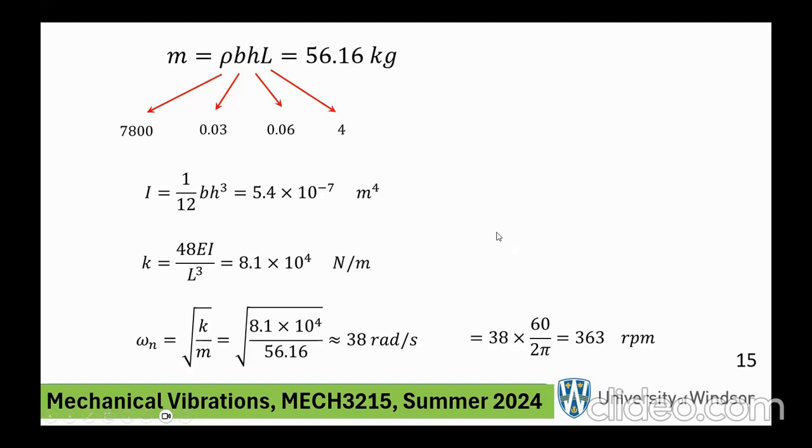Now, incidentally, in real life, there's damping present. In real life, you may have to operate at speeds that are higher than that, above that. And therefore, if you want to reach that speed, you have to go through that anyway. So the moral of the story is that in real life, if you want to increase the speed above that, you don't keep the switch or the knob at that speed for very long. Go through it very quickly. Okay. We haven't done damping yet. We will.